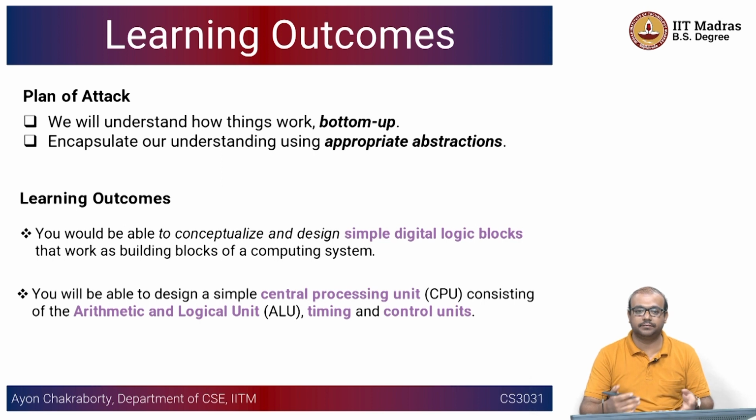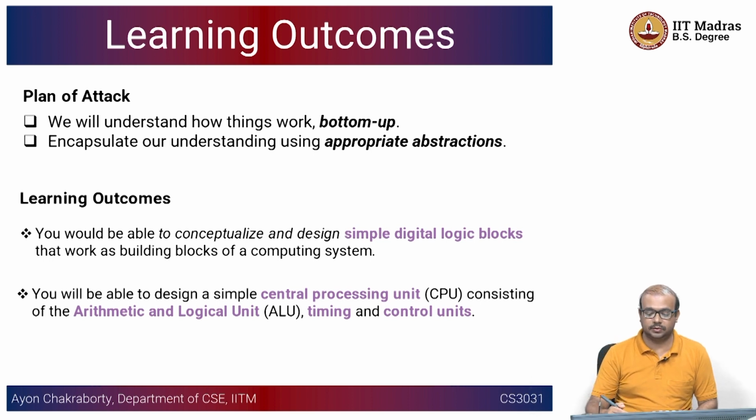the entire process of getting all these inputs A and B, passing them on to the ALU, instructing the ALU to compute the desired output, and communicating this output to wherever it wants to send it. It could be either in an internal register, or it could be writing it to some external memory and so on, and then fetching the next instruction, getting the next instruction and executing it, right? So the central processing unit is tasked with executing a program, and it is done.